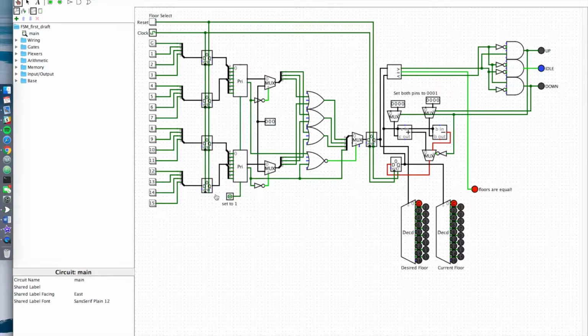There are a couple of things here that you don't actually have to implement when you're building the circuit. One of these is this pin that I have here. Essentially, these priority encoders in Logisim have a problem whereby, for example, if I'm using the bottom 8 here, in the top priority encoder the output, instead of being zeros, will be x's. I could not figure out how to fix that. There is even a setting where you can change this disabled output to 0, but because the input is enabled, it still outputs a floating value.